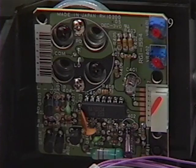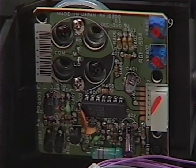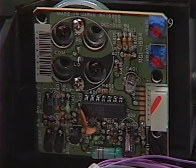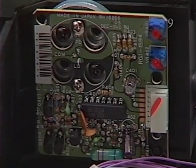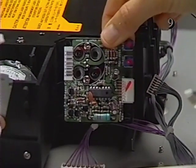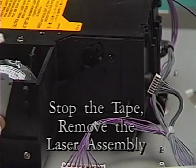Caution: do not loosen the two black screws located at 11 o'clock and at 5 o'clock when removing the laser assembly. If these screws are removed or loosened, the laser assembly loses alignment and must be replaced. Now lift the laser assembly out of the printer. Stop the tape and remove the laser assembly.